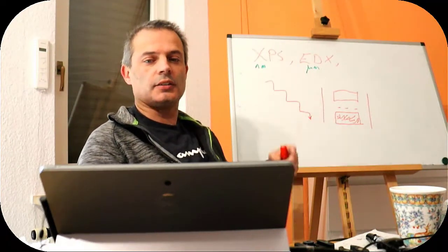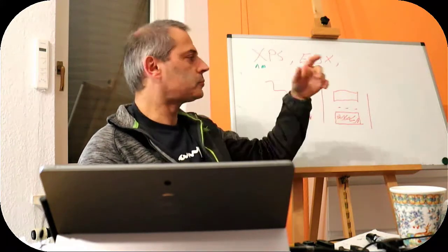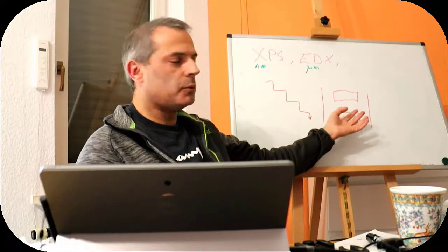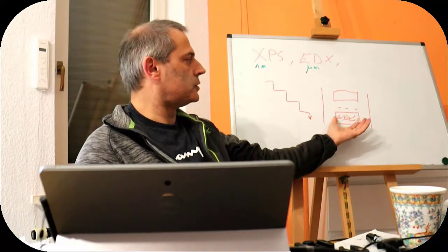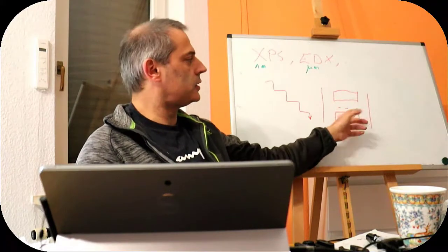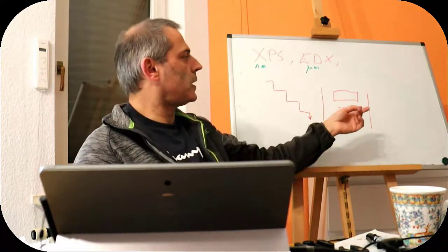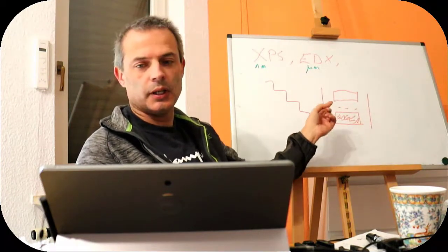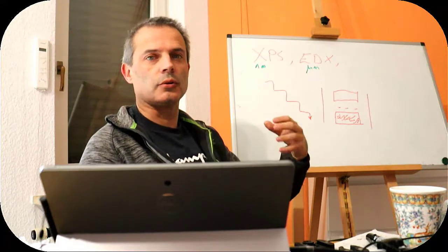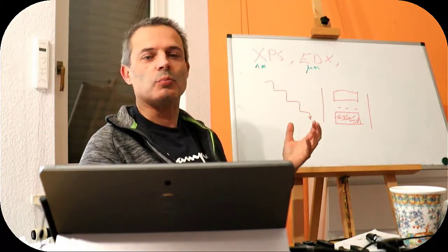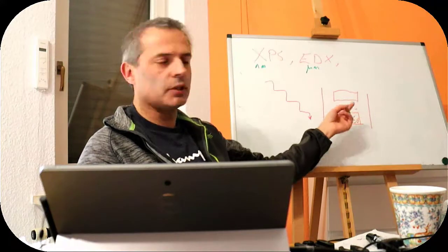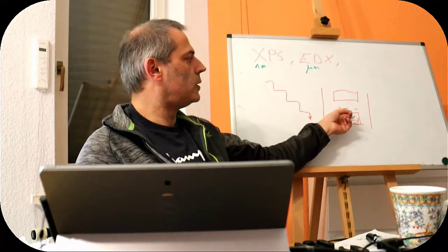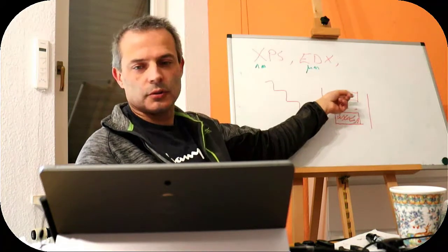What I've drawn here is a standard semiconductor, so just to remind you, the standard semiconductor has a valence band. It's the normal electron carrier band. It's got electrons in it, but they can't move around. It's got the conduction band, which is up here, and we might have some dopant in here, which are either doped with electrons or they're doped with electron poor things, so they either accept electrons from here, generating a carrier band in the center, or they donate electrons to the conduction band.